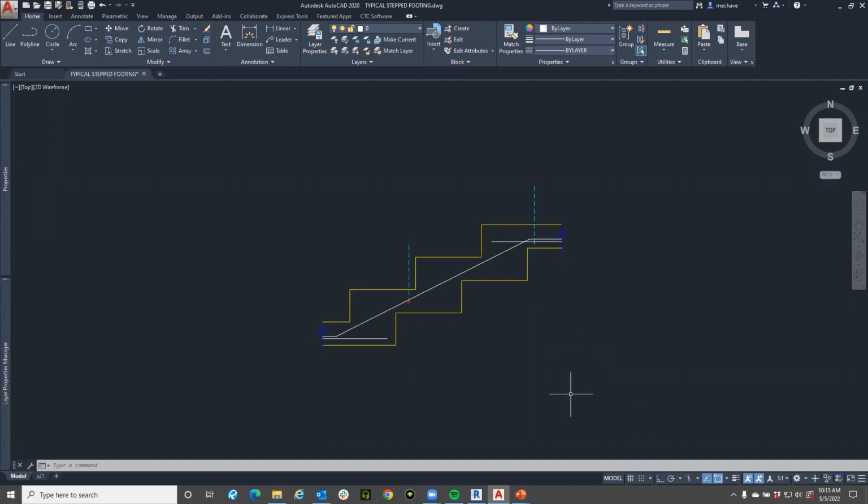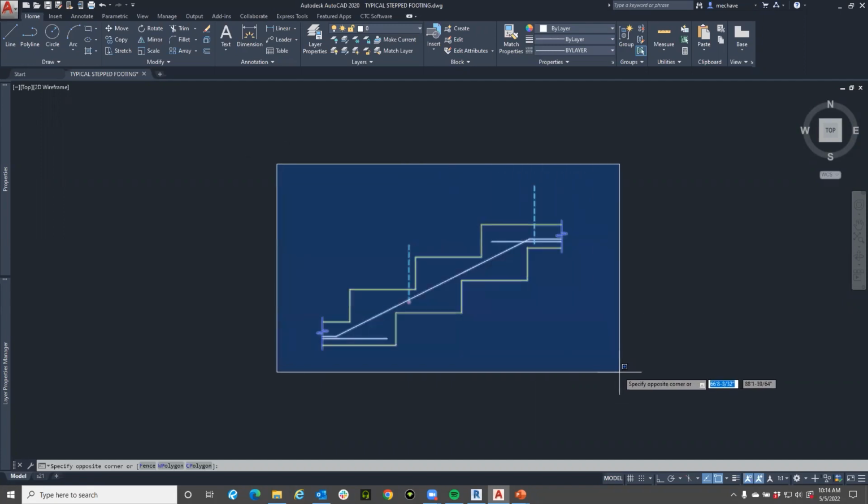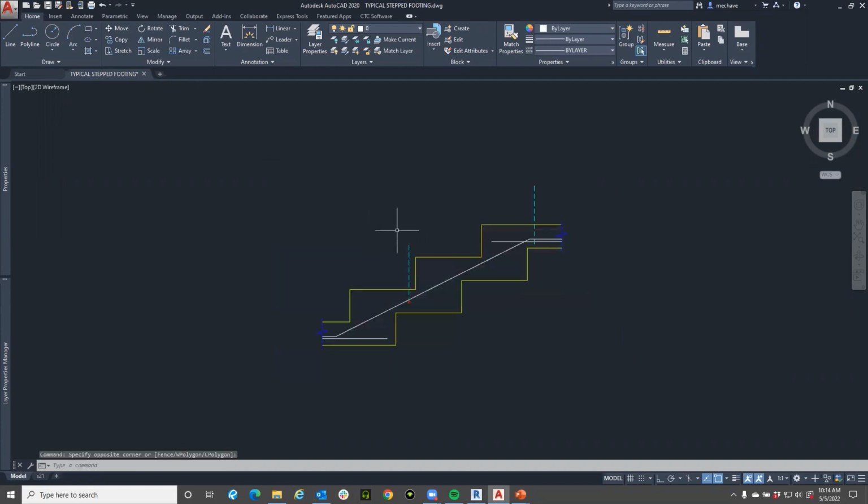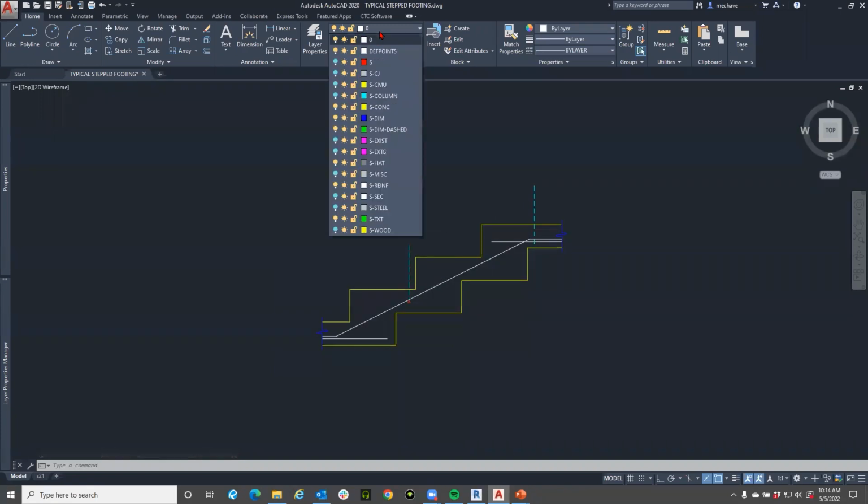Now from here, I also go through and run an overkill. What is the Overkill command in AutoCAD? When I first heard this, I was like, is this really a command? It is, everyone. Some of us have used it before, so we're probably like, yeah, we already know, Michael. That's fine. Well, first and foremost, one thing I do is check my layers, right? I want to make sure I don't have unnecessary layers in here. I'll do a purge, and I can go through and delete them out as well.